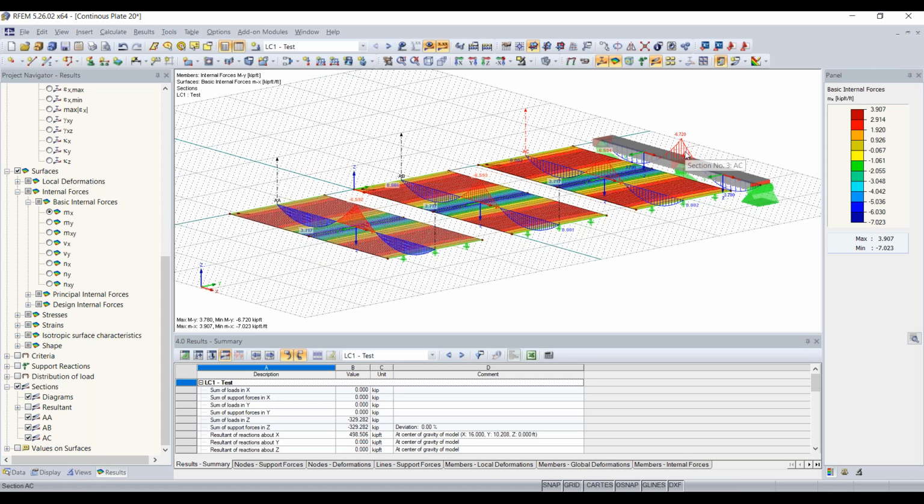The reason that this change happens is because the methods mostly used in school assume that each member has an infinite shear stiffness, when in reality there are some shear deformations happening when members or beams bend. So it's important to keep this in mind again when comparing hand calcs.